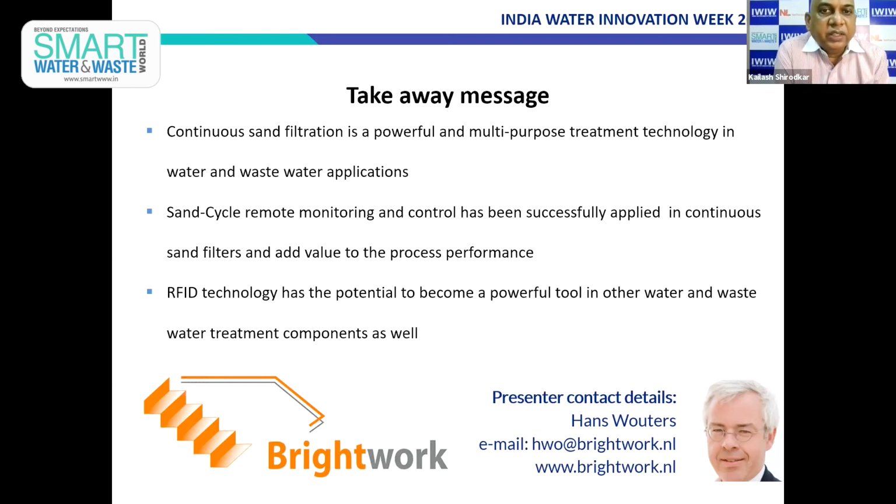I think the first question is: does the sand media have to go through any preparation or treatment before it is being used? No, we typically apply sieved river sand. The sand needs, of course, to be prepared before you can use it as filter sand, which means that it is sieved to a certain fraction. And then it can be used, and it will be used in these filters for quite a long time. So it doesn't need to be replaced because of wear and tear, because there is no wear and tear if the proper material is selected.